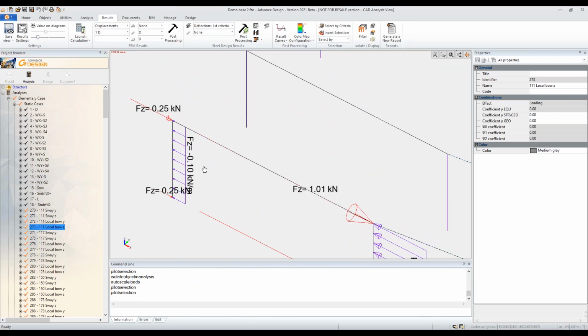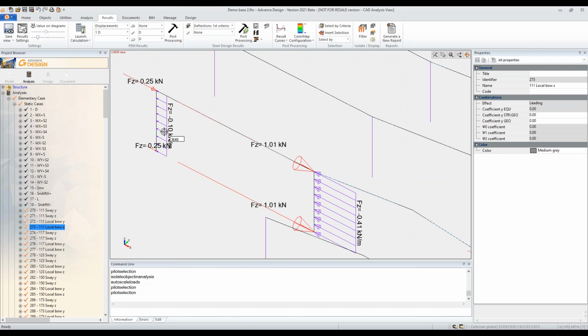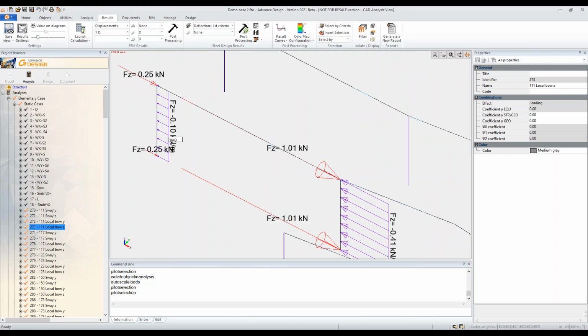And this time it's a set of linear forces which are balanced by some punctual load on top and bottom. And the intensity of this linear load depends on the buckling curve of the column in the strong axis and in the weak axis. But at no point did the user have to input the buckling curve.